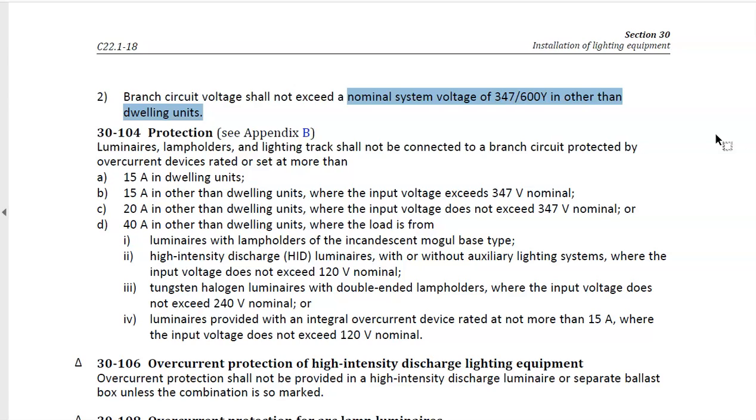And looking through all of these discharge lighting, the fluorescents, we saw that all of our tubes are rated in watts. So we go to a higher value of voltage. This is very dangerous, to go to this 347. You've probably heard people talk about 347 before and its dangers. The big danger with it is that it is high enough that it's not going to allow you to let go, so you get frozen to it, but low enough that you don't instantly burn off. Instead, you just stay on there and you slowly cook.